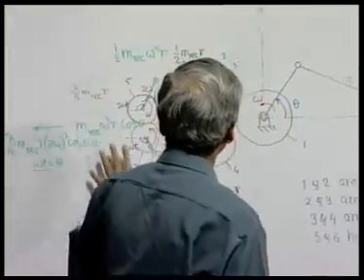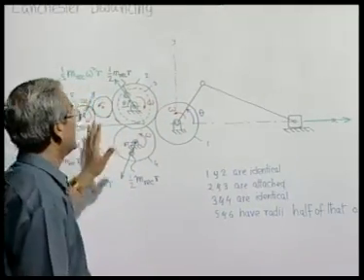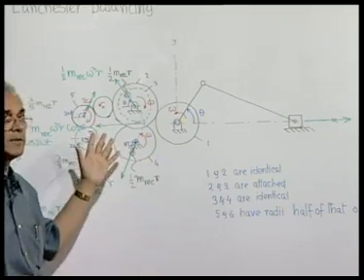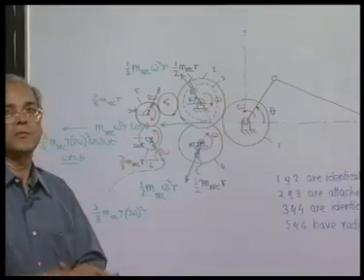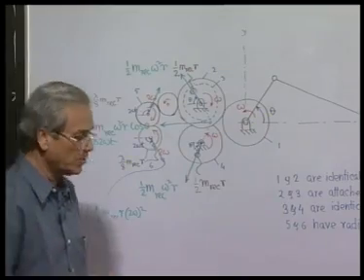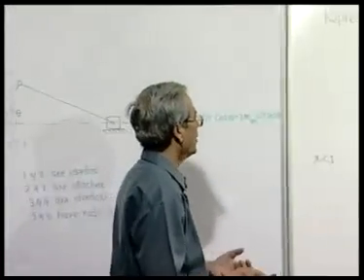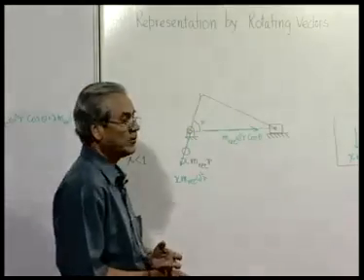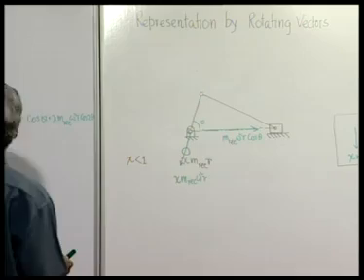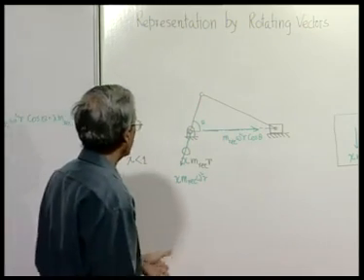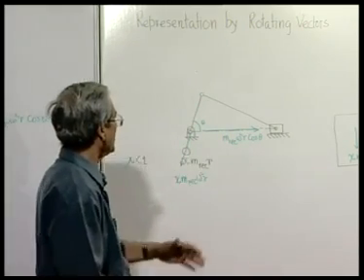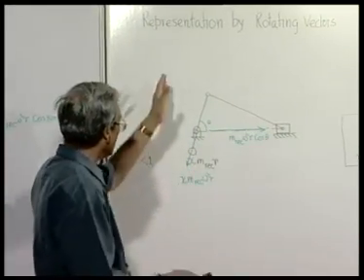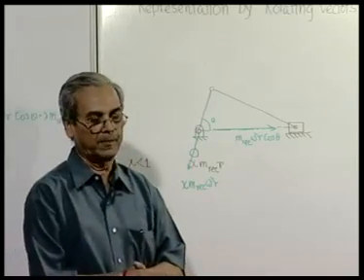However, of course, as I mentioned, this active balancing technique developed by Lanchester first, or proposed by him, is a very elaborate arrangement, and it is done only in very special cases. In normal situations, we always try to go for the simplest possible mechanical construction, that means in the form of a counterweight, where you can either convert the horizontal or x component of unbalanced force into a y component, or you partially balance it so that a little bit of x component unbalance remains and a little bit of y component is generated.